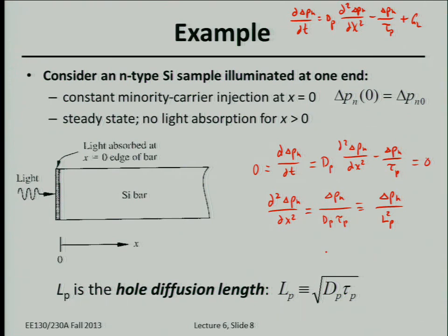Does doping affect tau sub p, the minority carrier lifetime? It'll increase? What did I say at the beginning of class? Do dopants affect minority carrier lifetime? No, they shouldn't, because it's only the impurities with trap energy levels near mid-gap. Extra dopants do degrade mobility, because they're ionized, and therefore the diffusion constant, but they don't affect the minority carrier lifetime. You can introduce other things like trace amounts of metal or crystalline defects into your semiconductor to degrade tau, if you wanted to make the diffusion length short for some reason.